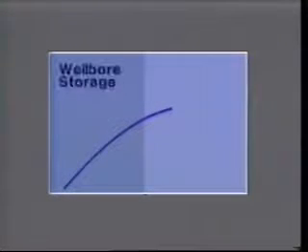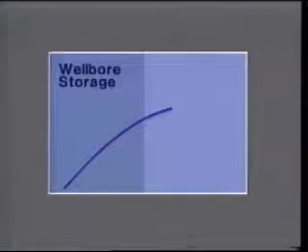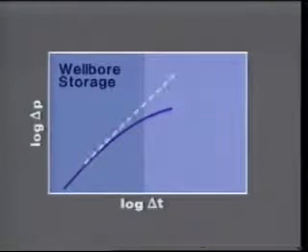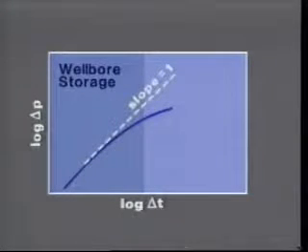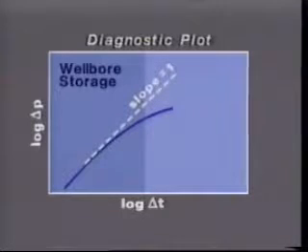In Period 1, the earliest condition observed, wellbore storage, exhibits its own characteristic pressure response shape. It yields a log-log straight line of unit slope at early time. This means that if the pressure data recorded during a well test has a unit slope log-log straight line passing through early time data, wellbore storage conditions exist. This is our first characteristic, or as it's often referred to, diagnostic plot.